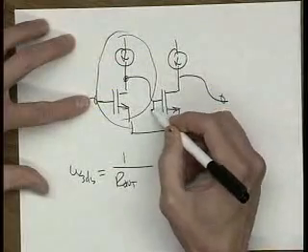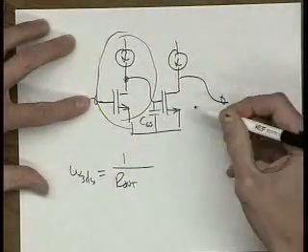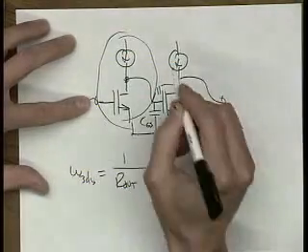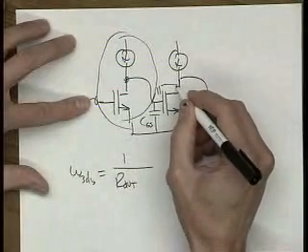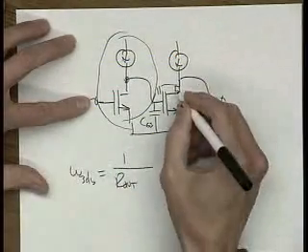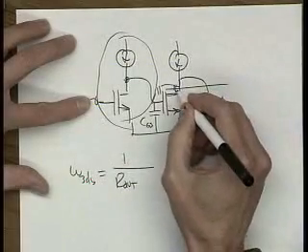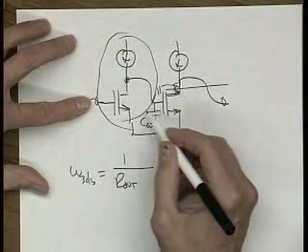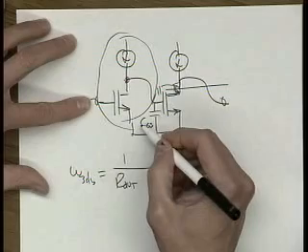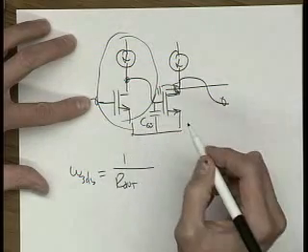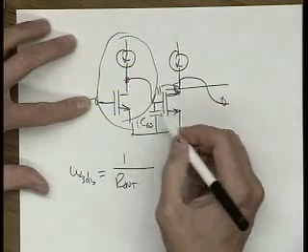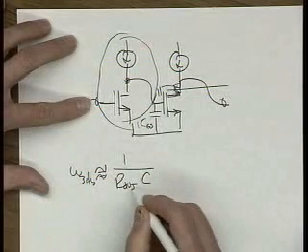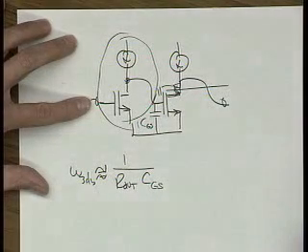Now, the capacitance of the next stage is going to be composed of CGS, and for this circuit it's potentially a C Miller, because you have a lot of gain in this next stage. Of course, we can get rid of the C Miller by cascoding this. I'm trying to get fundamental limits in some sense. So I put a little cascode device here, and I end up seeing really only CGS. There's CGB and some other things, but they're pretty small compared to CGS. So CGS pretty much dominates. So very, very roughly, omega 3 dB is R out times CGS.